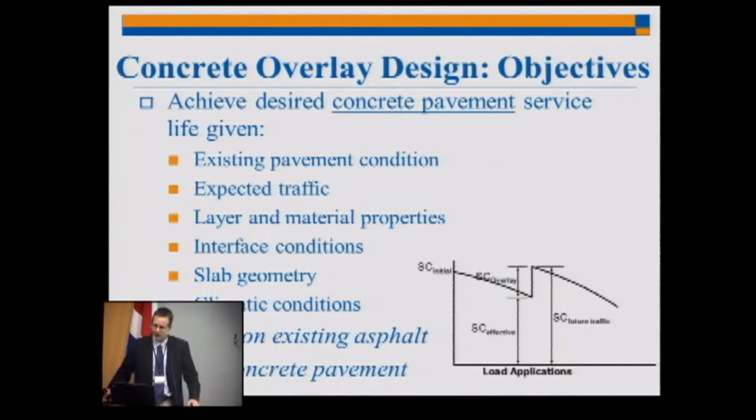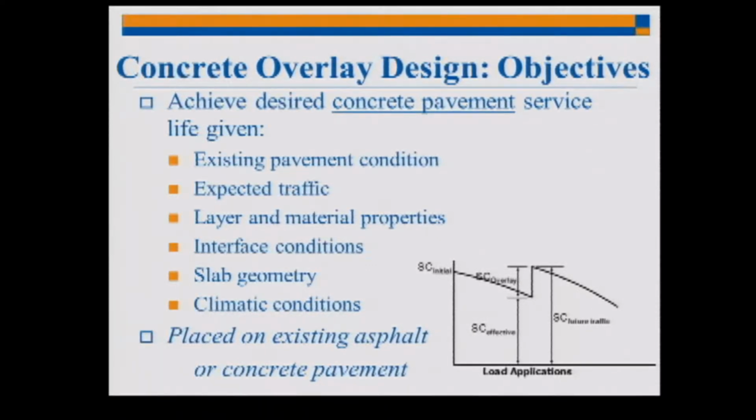So our objective in designing overlays is providing a design that gives the agency or the owner the life that they want. We design pavements for a life of 10 years, 15, 20, 30. So you have to define what kind of life you want to achieve with your overlay. For certain conditions, you may only want a 10-year design. In other conditions, you may want a 30-year design if it's a high-volume road, one of your highways or your arterials.